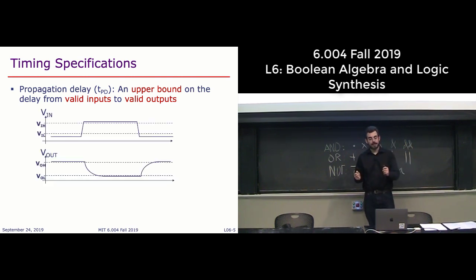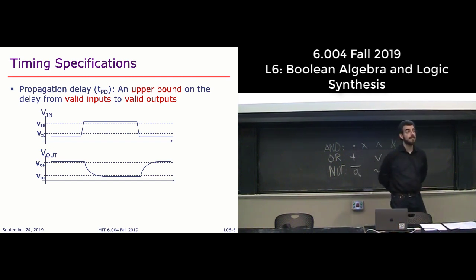So if you have something like an inverter, right, you can feed it a pulse with a rising voltage, and then a falling voltage transition in the input, right? And so what you'll see, depending on the particular implementation of your inverter or your particular combinational device, is that there will be some time during which the output does not change, and eventually it starts falling. And after some time, it reaches VOL, right? The output level that we said was representative of a valid digital output, right?